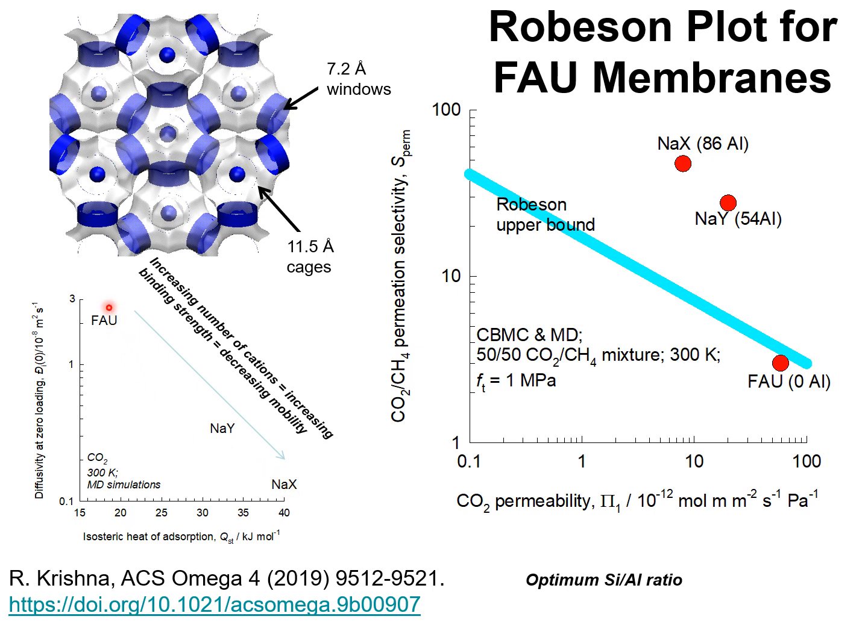So increasing binding strength leads to decreasing mobility and decreasing CO2 permeability. So in practice, the degree of ion exchange in cation exchange zeolites can be tuned to optimize the membrane performance.